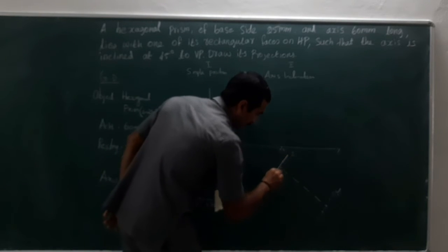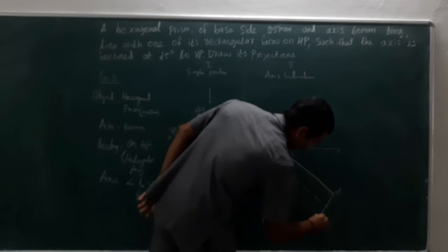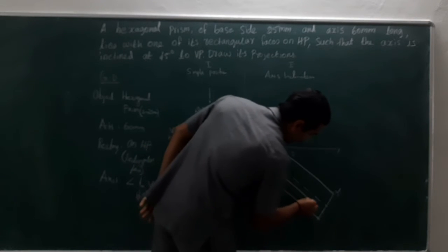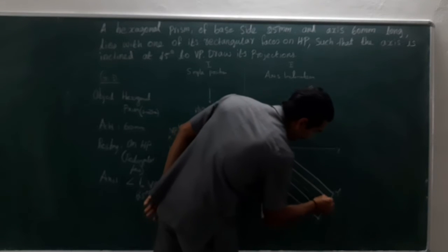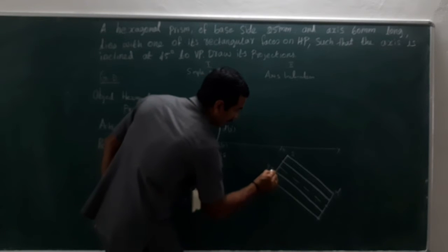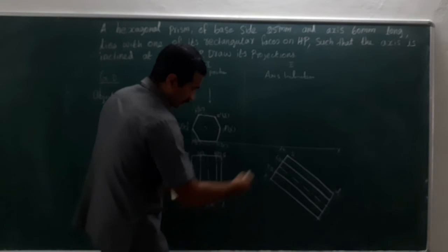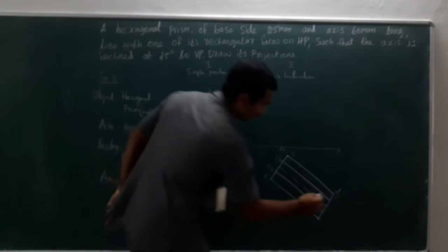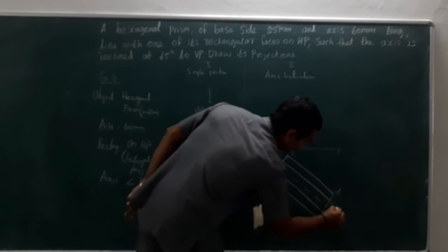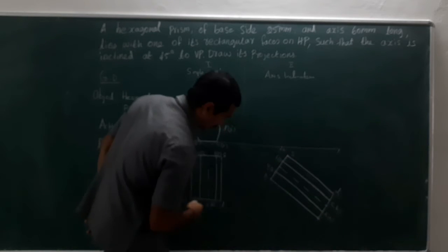Now draw the object lines using an H or HB pencil. Draw all the lines. Then transfer all the points here, that is the notations. So P, this one could be U1 and Q1. Next could be T1 and R1. The front face, that is D, and here this could be E1 and C1. Next, F1 and B1. Next, A1.